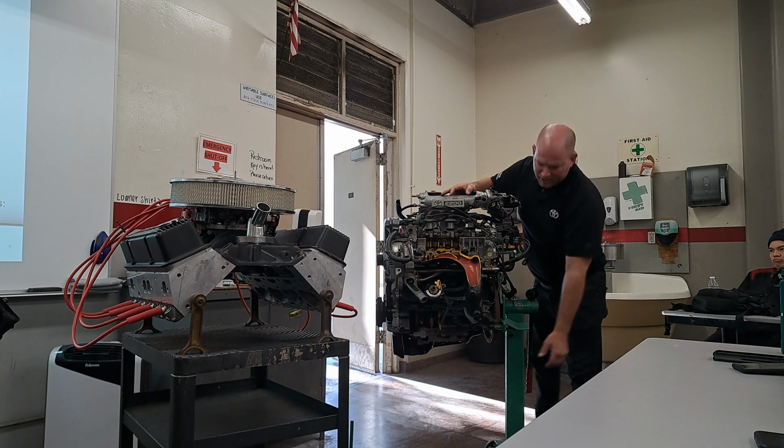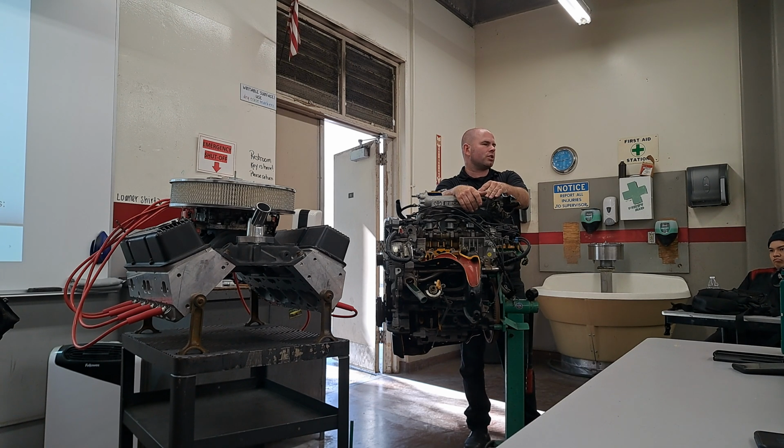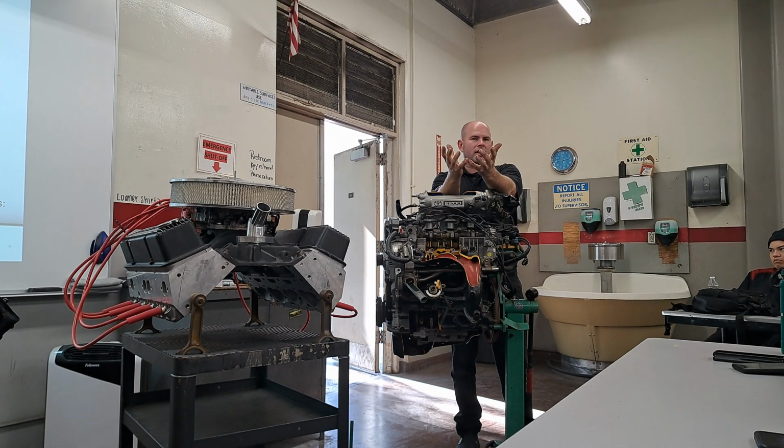Right, and then from there, if we go a little bit lower, you get down into the oil pan, and the oil pan can look a lot of different ways. This one's actually just steel. But on the newer ones, especially aluminum block, you're going to see an upper oil pan that's aluminum. It's structural. Those are a pain in the butt to change. And then on the bottom, you just have a little stamped steel one that's pretty easy to see all the bolts. Those are a little easier to change.